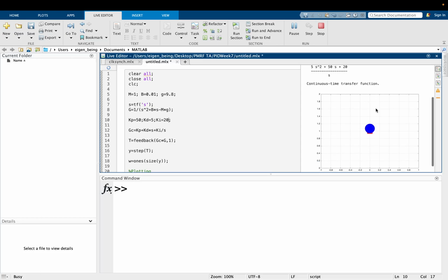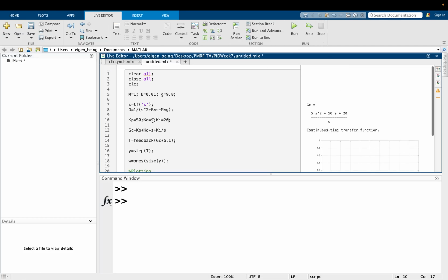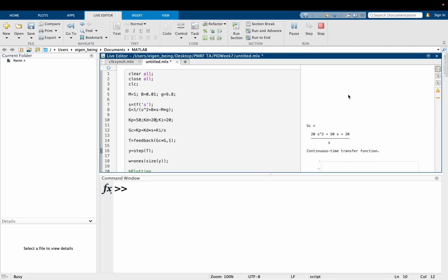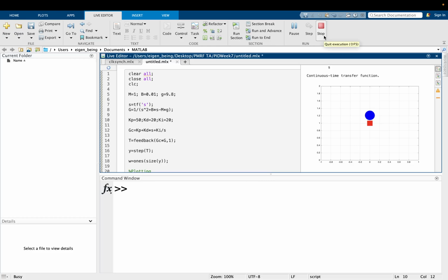Okay, now the steady state error has decreased. See, but there are oscillations. Now it is perfectly at where I want, correct? So if I increase my kd, the derivative gain, what will I get? Perfect, almost perfect. It still oscillates, but it comes back. So it will obviously come back, but it will be very slow because of the derivative gain.